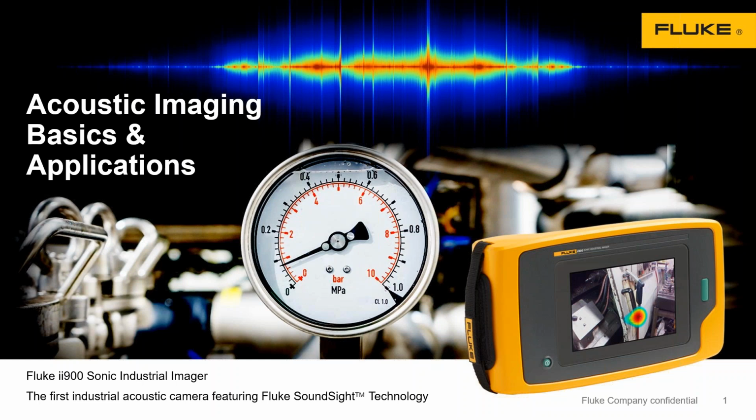So the reason why you should care about this kind of product and this kind of technology is it helps you easily identify and document where these losses are occurring, whether it's compressed air, argon, nitrogen, or anything else that you've got on there. If you're leaking it out and it's important to you, you need to know where to actually go to try to fix it. And sometimes, as you're getting to be my age, you're not hearing that hiss quite as much as you used to when you were younger.